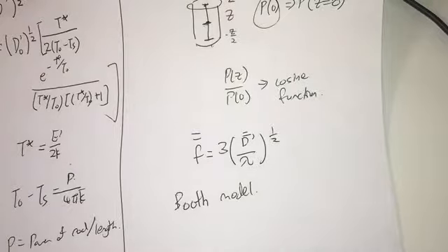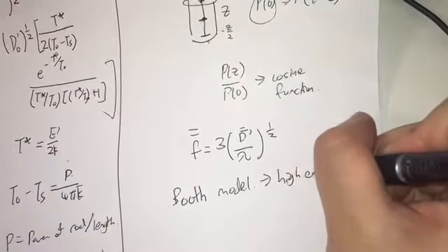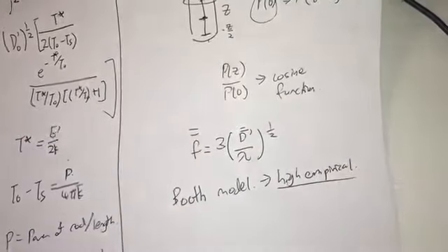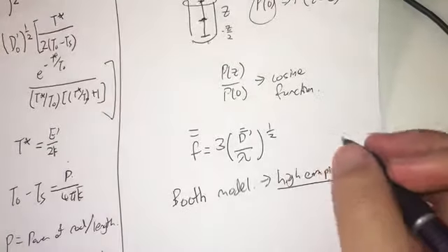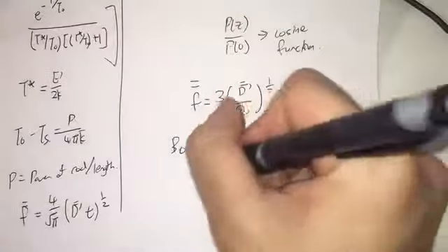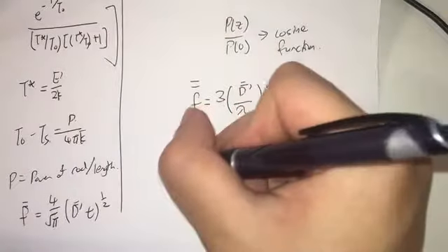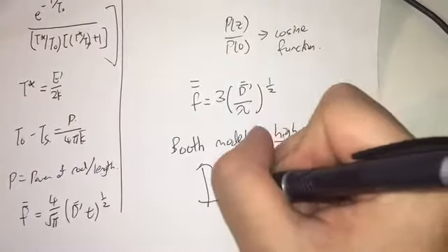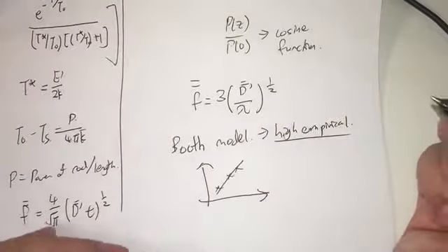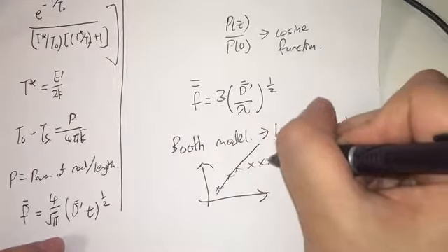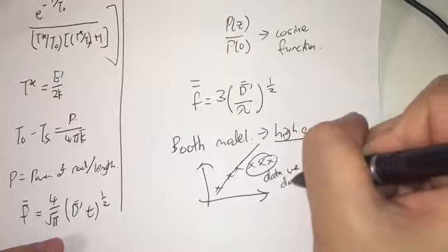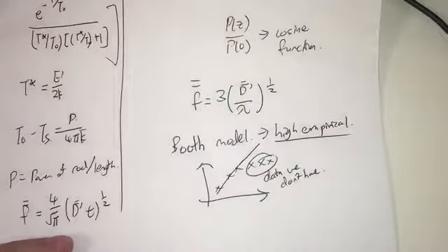So that's one way of thinking about fission gas release. Now the weakness of this model is that it fails to predict fission gas release outside the data range. So this is very highly empirical. It cannot predict gas release rates outside its data range. What it means is that if, let's say, you have a gas release versus time plot, and this is the data range with this hypothetical linear trend, you cannot extrapolate. Sometimes the actual plot may be like that, and this is data we don't have. So that's the idea of what it means.